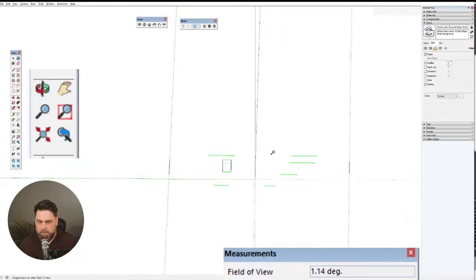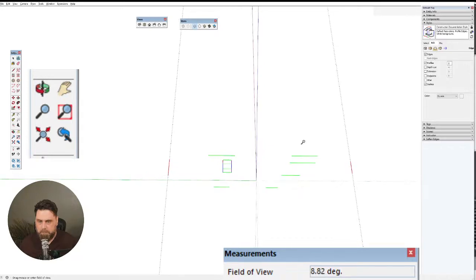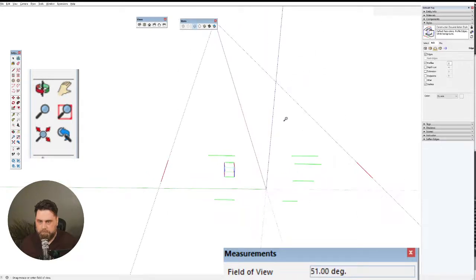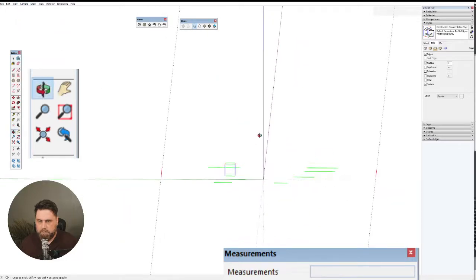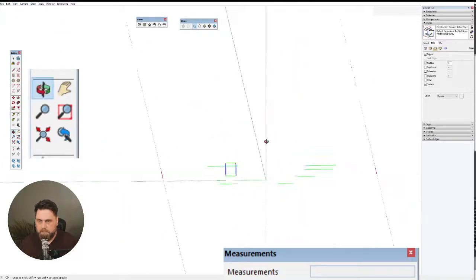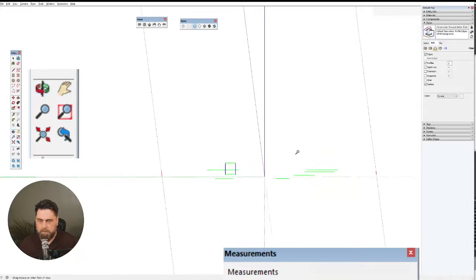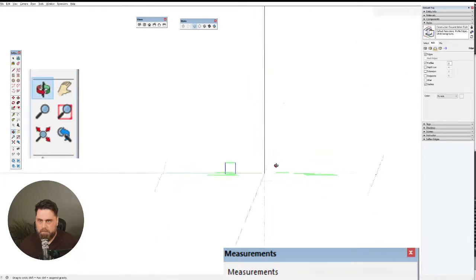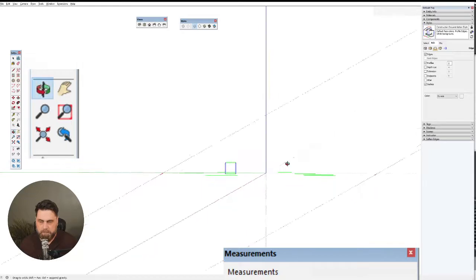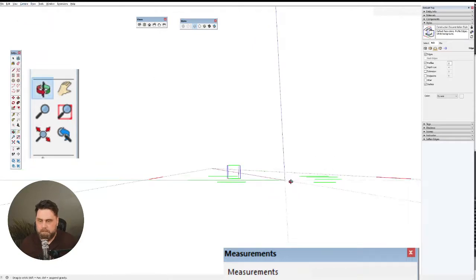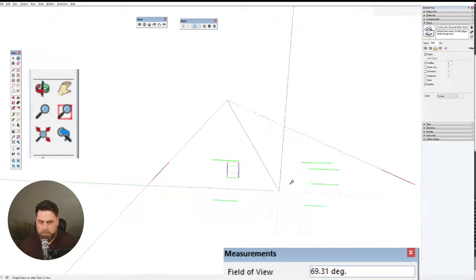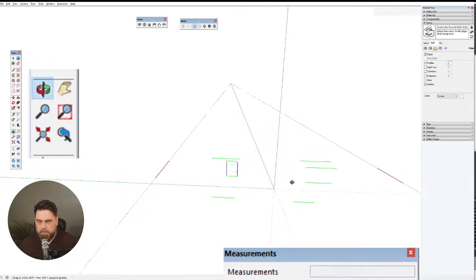But as we raise this up, watch how they start to angle. And then again, camera parallel projection, there's no vanishing point. It's a field of view of 0. So we can't rotate down and see where this disappears in the distance because now they're truly parallel from each other. All right, so let's go back to perspective. Again, I work around 50 to 70, somewhere in there.